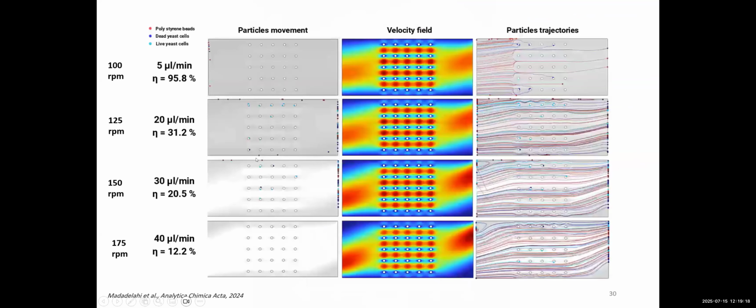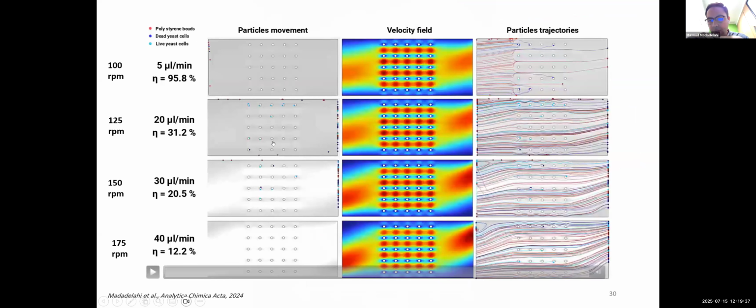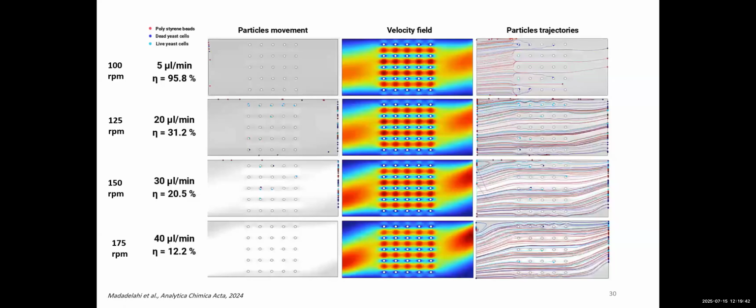Okay. So the electric voltage boundary conditions for the one on the top, was it set at the bottom, or was it given directly to the walls of the electrodes? To the walls of the electrodes, because there we didn't include the electrodes themselves, right? This is a pure fluidic, let's say, modeling.